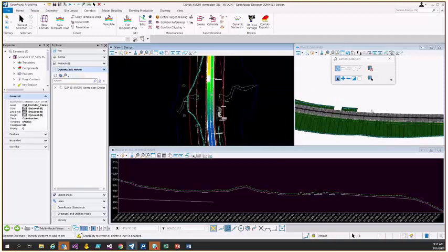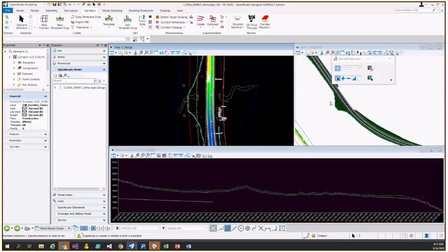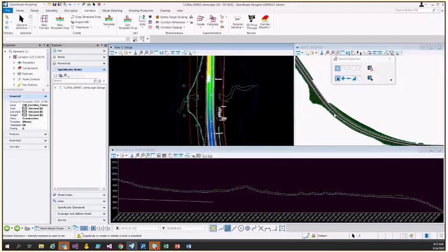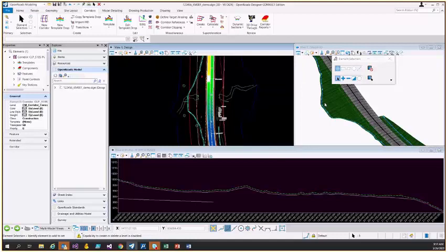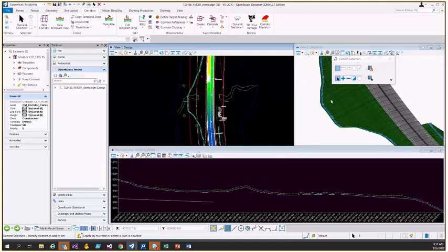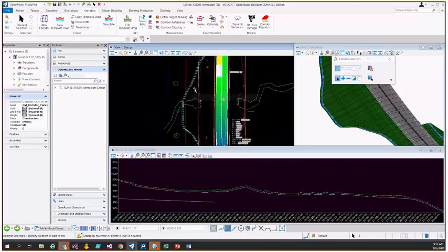So I definitely kind of made some blunders in there, but I guess that could help explain what's going on here. So you see there's that ditch, and so really to recap that, we are using a template to give us kind of the starting point to create a ditch profile.